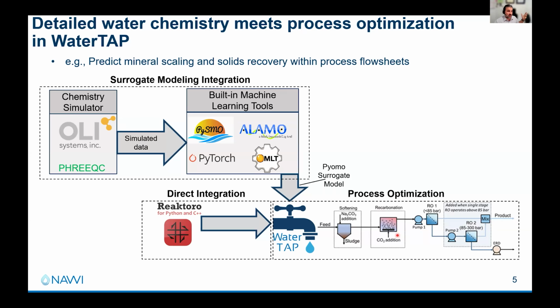I just want to point out, using some of the existing free tools out there from, let's say, some membrane manufacturers, you could plug in your specs for your, let's say, your RO treatment train. You could plug in your feed water composition, and you'll get back what the supersaturation ratio may be, the saturation indices with respect to certain mineral scalants, right? So it's sort of a post-process result.